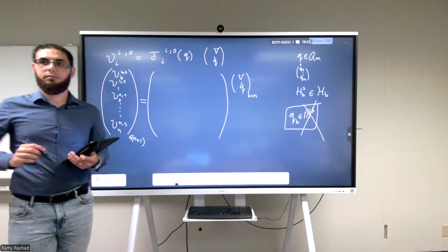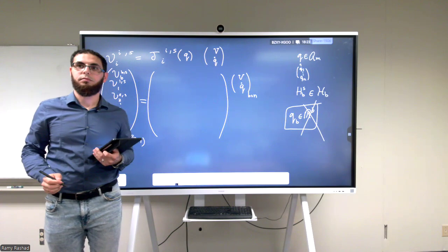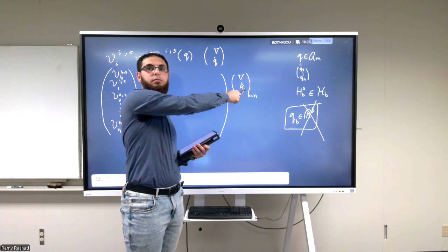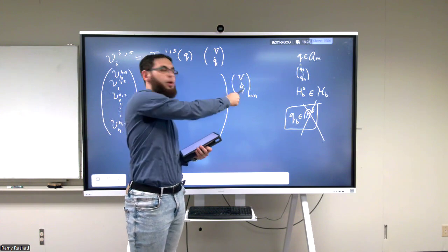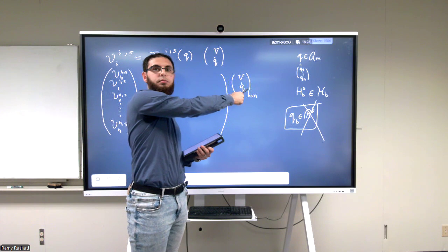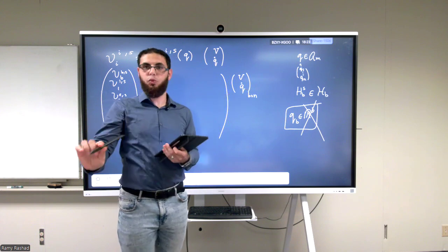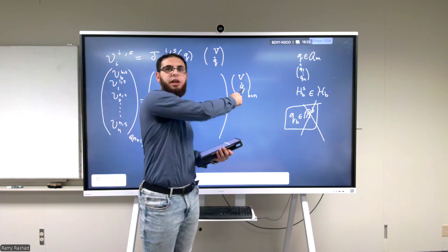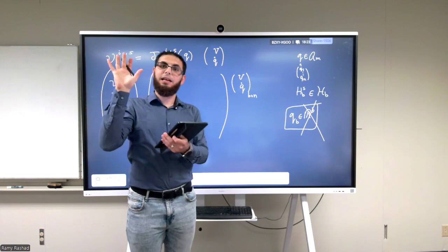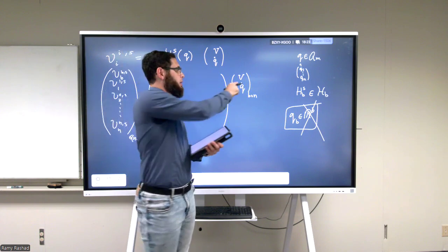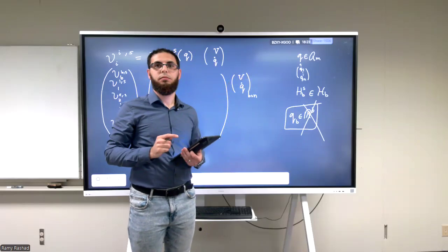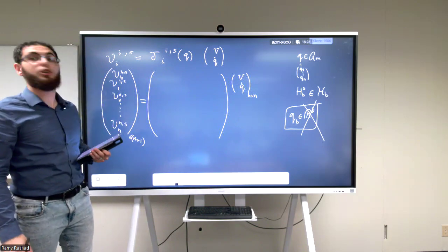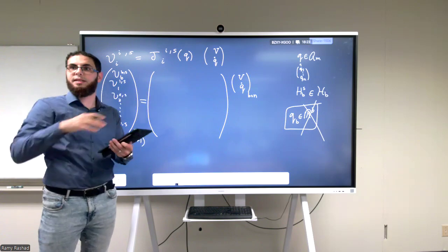So what's the difference? I'm really not understanding the difference between the small v and the Q dot. Base motion, manipulator joints motion. So if the base is fixed, not moving, and the manipulator is doing stuff, these are zero and these are changing. If the base is moving and the manipulator is locked, these are zero and this is moving. Here, is the Jacobian supposed to be a function of Q or Q dot? It's a function of Q. The Jacobian is always a function of Q. When I write it down, you're going to see why.